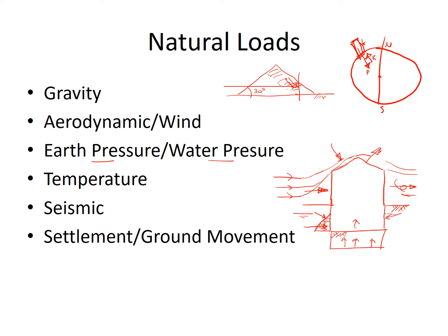So similarly, the water table would typically be the same on both sides of the building, and we will again get a water pressure on this side. These earth pressures and water pressures obviously are either here or they're not. They can be present. The water table can rise up or down, and the wind can drop off to zero or be at its full design load.